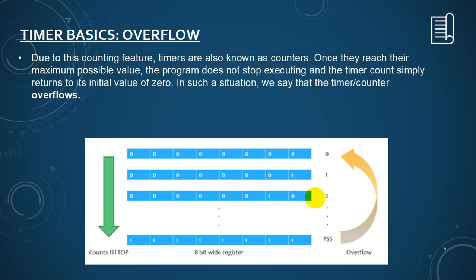So in this case, if you use 256 counts, and each clock takes more time, then you can count for a longer time. That is not possible with the main timer. That means in the main timer it will overflow many times in a second. It is not possible. So you need to keep track. When it overflows, one count, another overflow, another count. So this is one way, overflow. Overflow is one technique that you keep track of the counting.